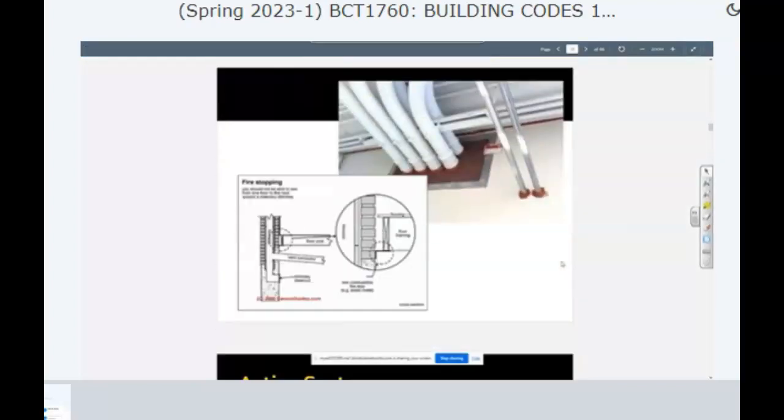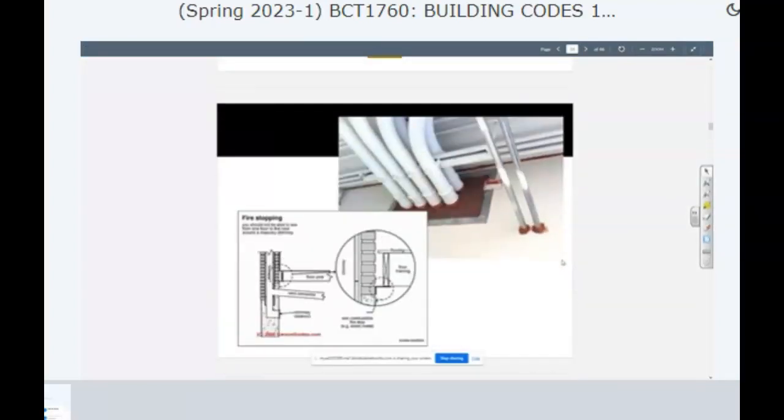Okay, so we just looked at fire stops. We're looking at ways that we can prevent the fire from spreading into our adjoining room. And we're also going to start thinking about not just vertical, not just what's happening next door, but also what's happening upstairs. And you should not be able to see from one floor to the next around a masonry chimney, which is one of the weak points. Things that go up vertically, and that's a pretty good example.